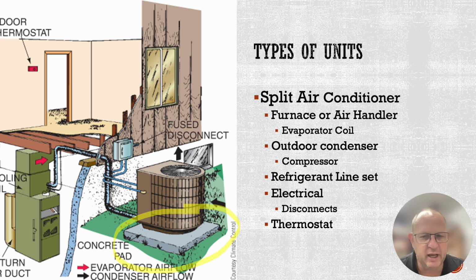This is going to help the oil within the compressor to stay level, plus the appearance of it being unlevel from one position to another really makes it look bad for the homeowner, bad for the technician who decided to leave it that way. So we want to make sure that we are hooking these units up and maintaining them in a way that the appearance of them is professional in that application.